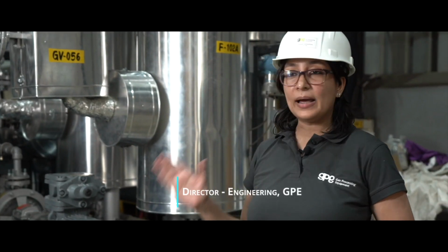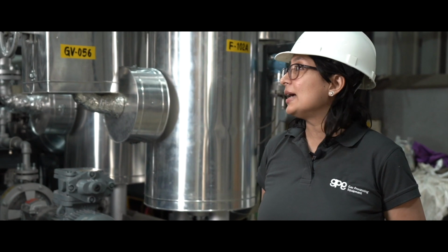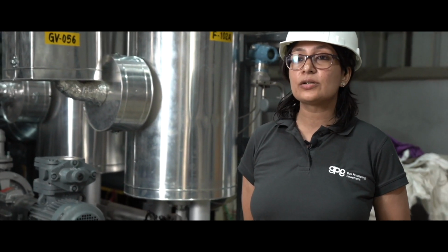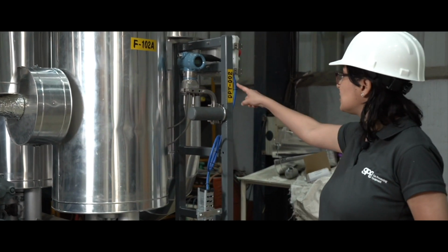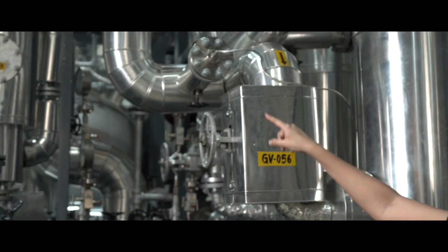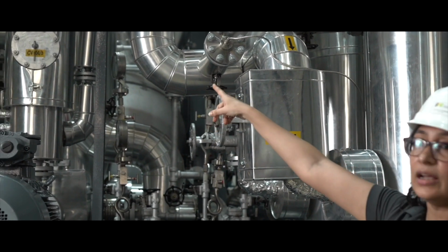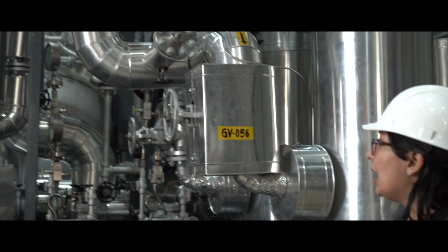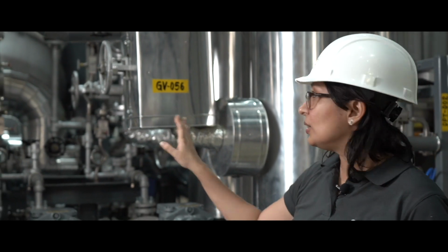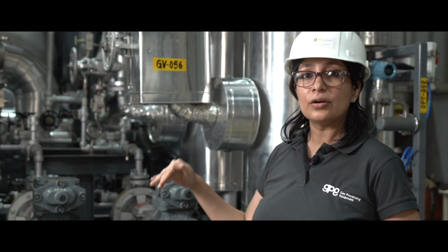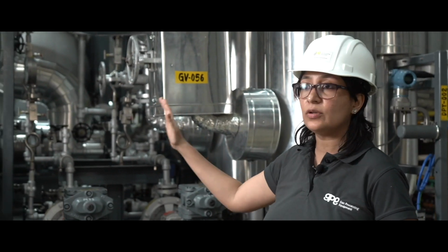Yes, this entire package is in hazardous area zone 2, gas group IIA, IIB, T3. The design temperature is 330 degrees Celsius and the pressure is 15 bar gauge, which makes it a 300 class execution. Because of the very high temperature, all the transmitters used, which are the pressure transmitters and the flow transmitters, are with diaphragm seal. The pressure gauges are with siphon and diaphragm seal. As you can see, all the pipes, the vessels and the towers are insulated, and the insulation thickness is around 100 mm to 150 mm in various parts of the package.